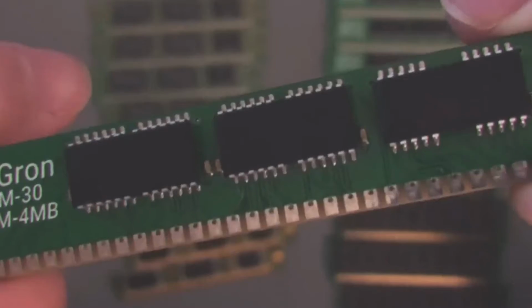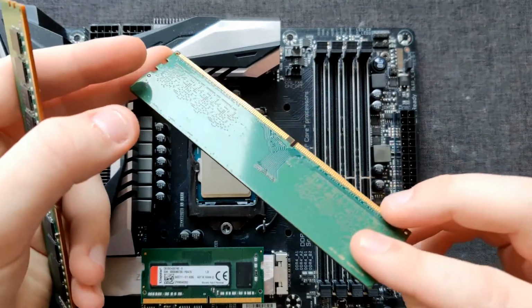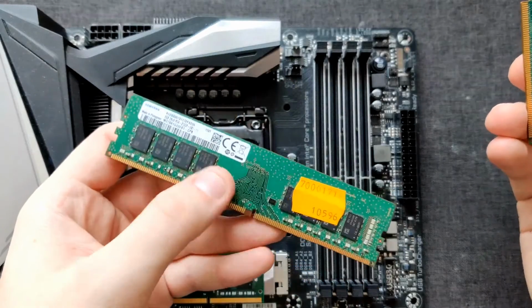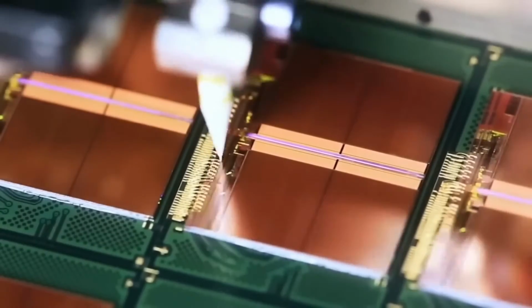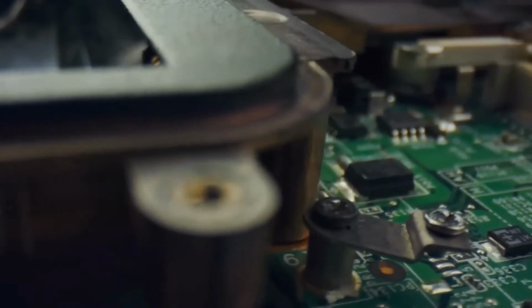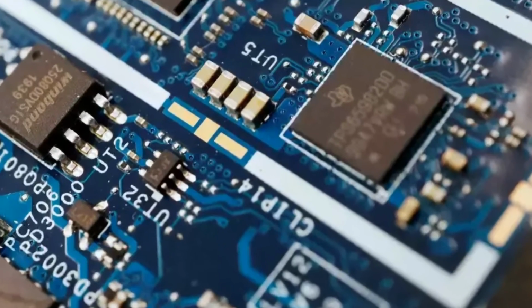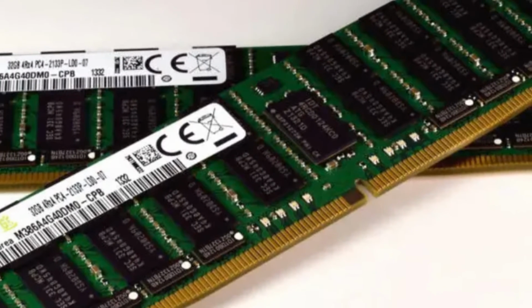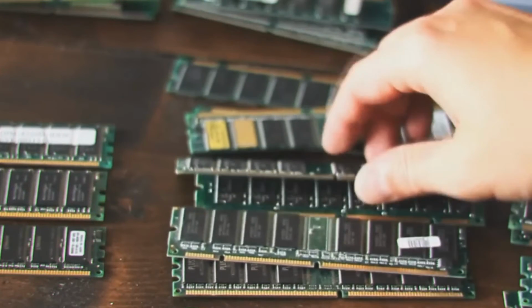DRAM has two main advantages over SRAM: price and data storage density. For example, a DRAM module will cost about 200 times less than an SRAM module of the same capacity and will have about 20 times smaller dimensions. These figures are quite conditional, as these devices rarely have even approximately comparable memory capacities. If we're talking about tens of megabytes of memory for SRAM, then in the case of DRAM, it's already about tens of gigabytes, which is 1,000 times more.